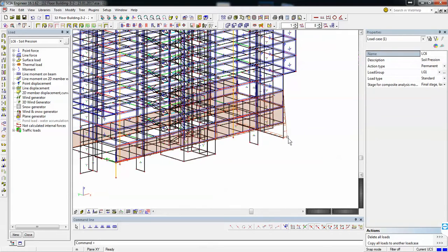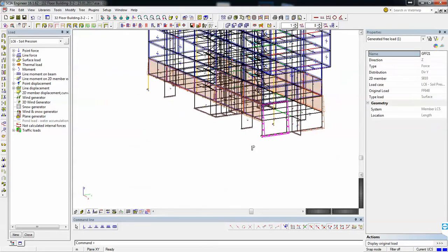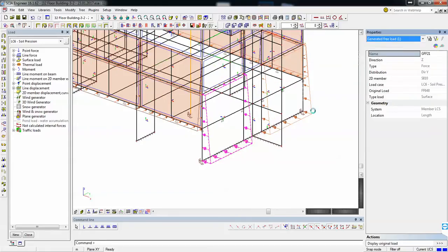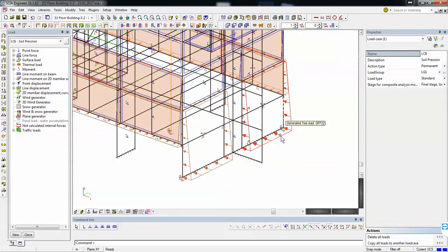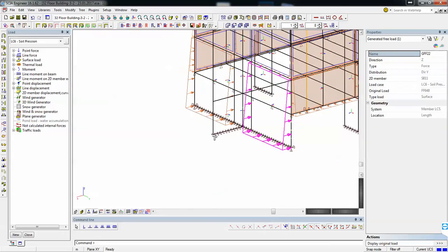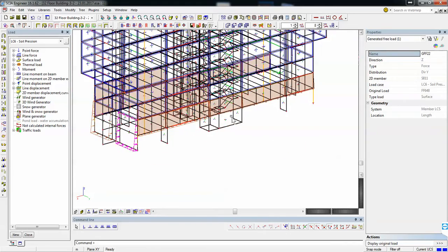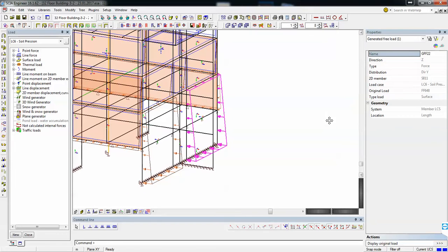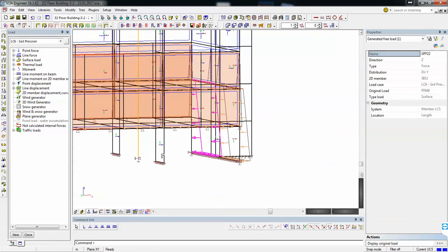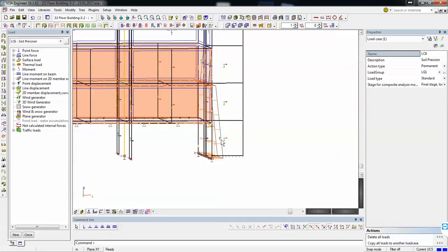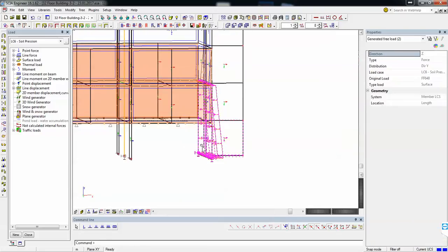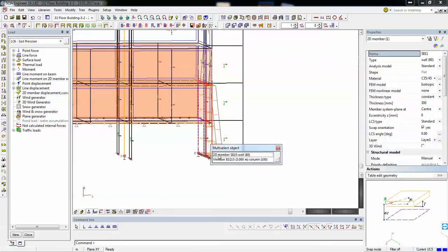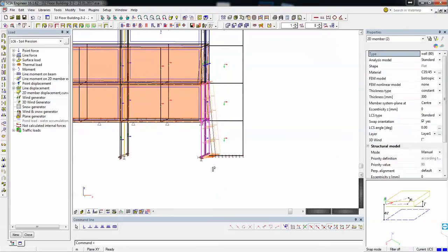Here we'll need to check that the soil will have pressure on one side. Now there's a small observation here. It looks okay, but you will only load the soil on elements that don't have soil on the other side. So in this instance, for this portion, you have soil on both sides, so there's no loading from the soils.